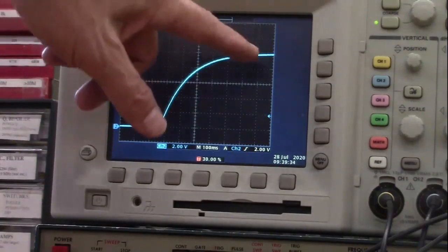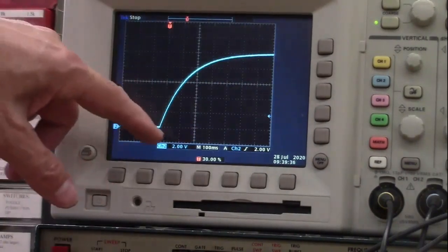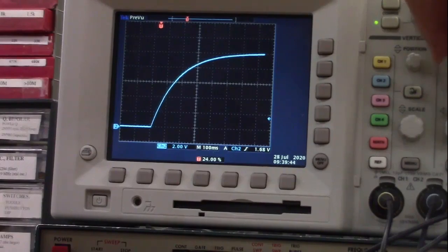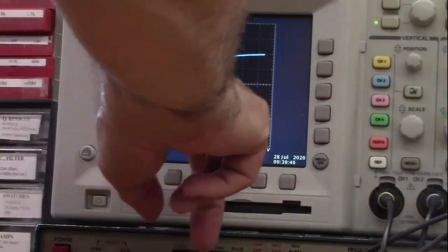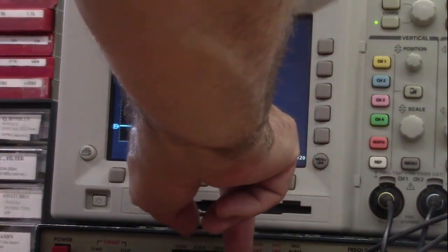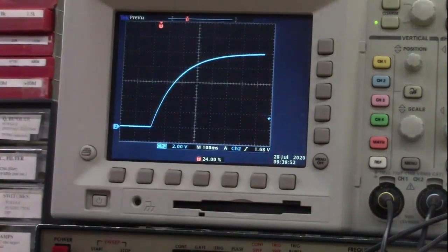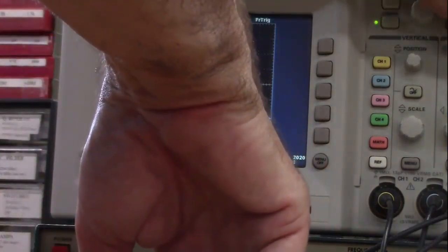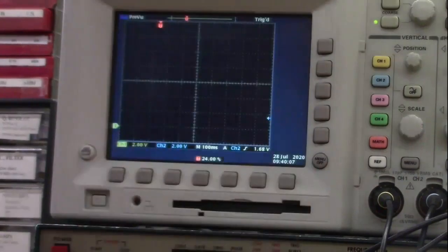We end up at approximately 10 volts. But it takes quite a while. Let's go ahead and position this so it's easy to see how long it takes. So it looks like we're up at 10 volts, maybe out here, which is 1, 2, 3, 4, 5, 6, say 7 divisions, somewhere around 700 milliseconds. Now we can compare that to the current source. Let me try and release both buttons at the same time.